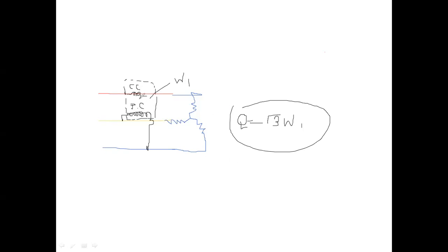Actually, in your wattmeter, there is a connection like this: M, L, com, V. In normal cases, M and com are short circuited or connected, but whenever we are measuring reactive power, this connection should be crossed, open.